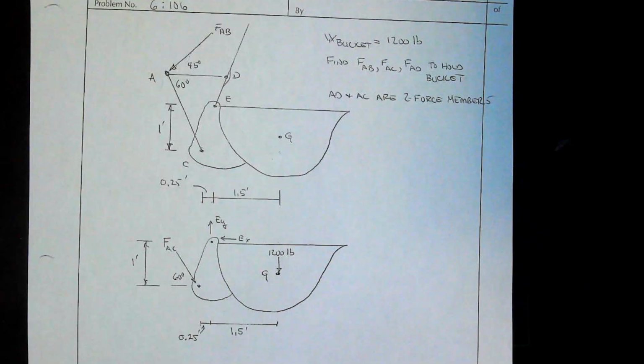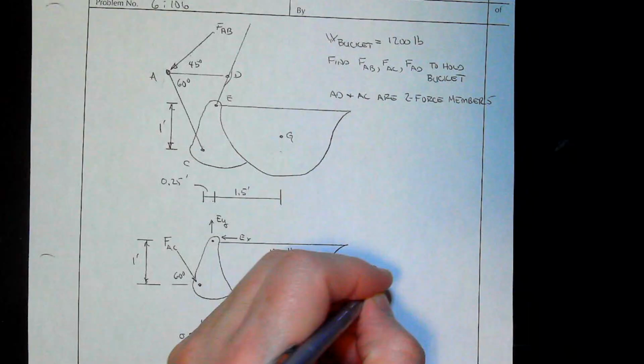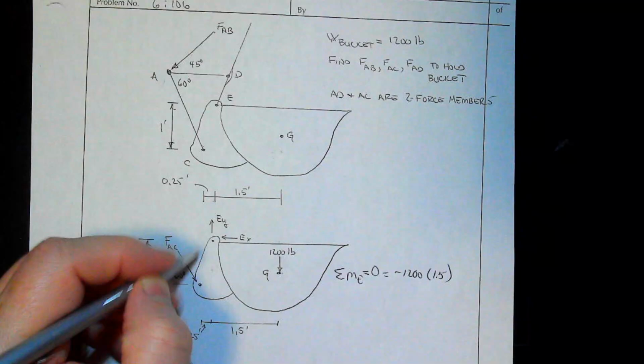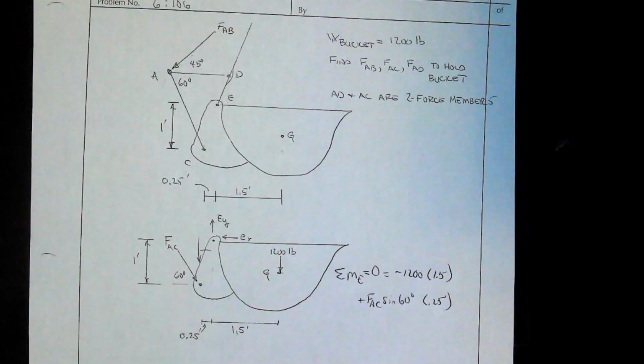And by doing that, that moves this down, and this rotates about this point D. This is a rod here. And then that causes this force to be pushed down into here, which then makes the bucket stay level, as it were, as opposed to coming down, okay? So we can see how it works.